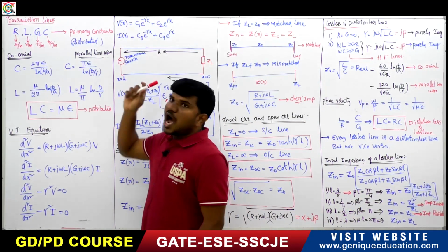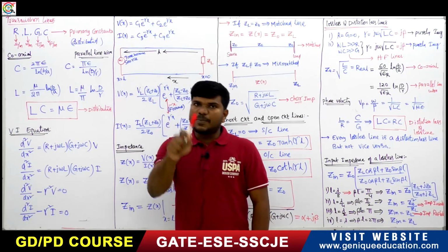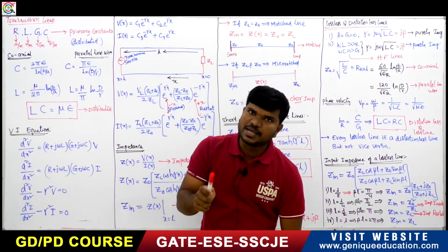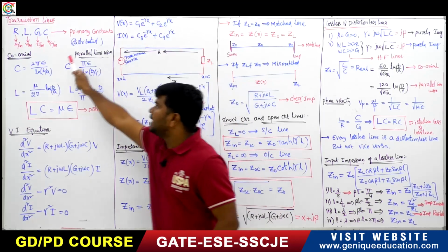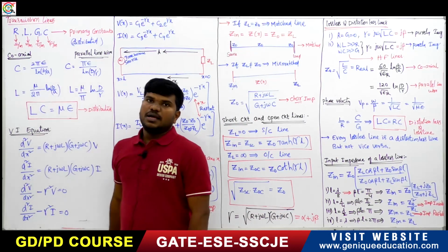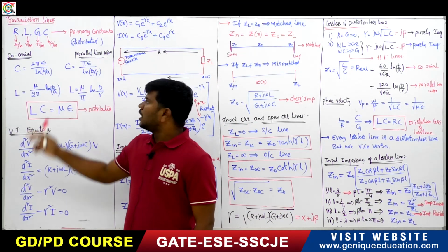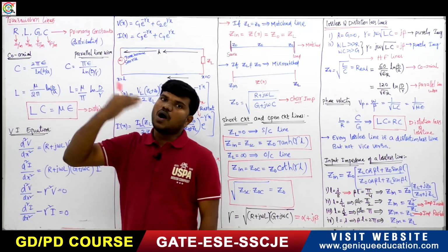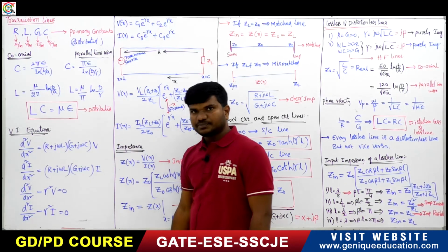So that's why we have to compare this geometry with that. Already we know the concentric cylinders capacitance. What is the concentric cylinders capacitance? 2 pi epsilon h divided by ln b by a. Already we know what b is. b means the outer conductor radius.